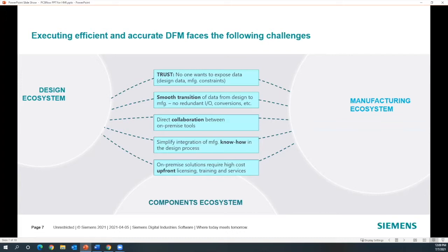So what we see happening is either people just give up and they don't do a real DFM analysis, I would say any DFM analysis, or they decide to do something which is average. They create some type of manufacturing constraint file, but it's not really representative of the manufacturing process which their design is going to go through when they go to their manufacturer A. Now, let's say they modeled it 3-4 years ago, and now in order to be more agile, they have bought 2 more suppliers. Well, have they changed the manufacturing constraints files?